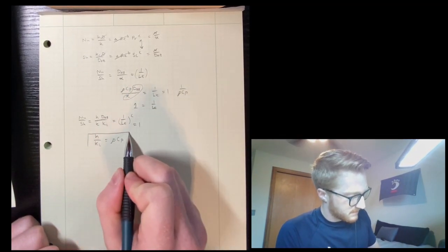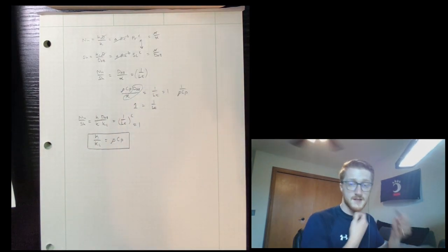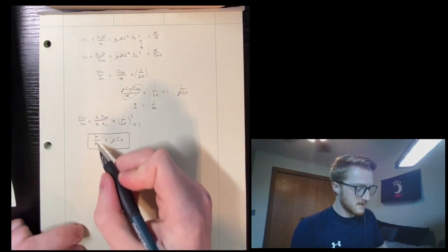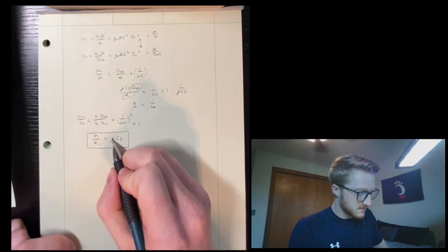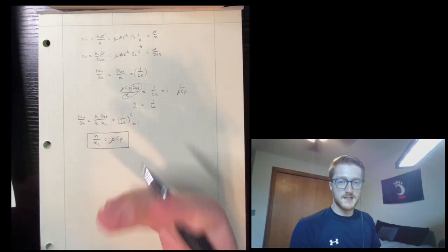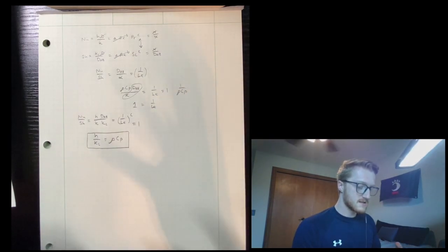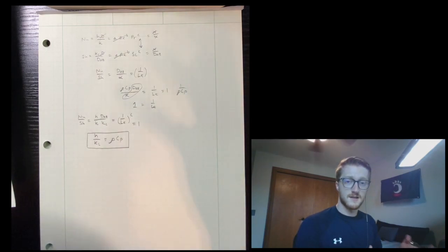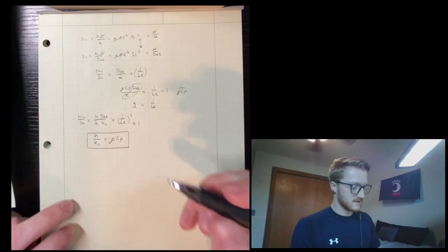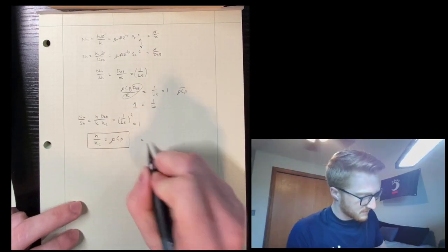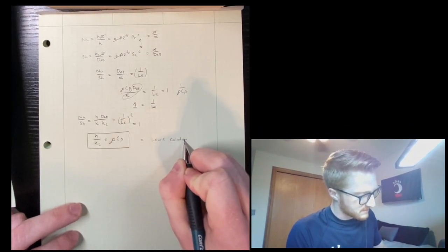And this is pretty crazy, considering that we have a mass transfer experiment and a heat transfer coefficient, and we can relate them via the heat transfer coefficient and the mass transfer coefficient. That's just going to be equal to the volumetric heat capacity, and it isn't going to rely on the size of your characteristic length, your d, and it's not going to rely on your Reynolds number or your velocity of the system. And this is what is called the Lewis relation, which is very important in chemical engineering and a good thing to know.